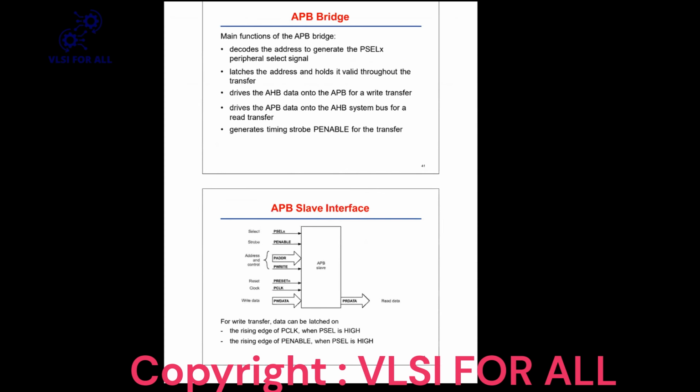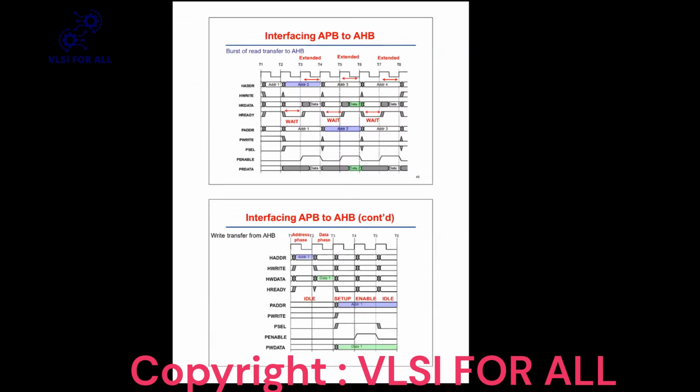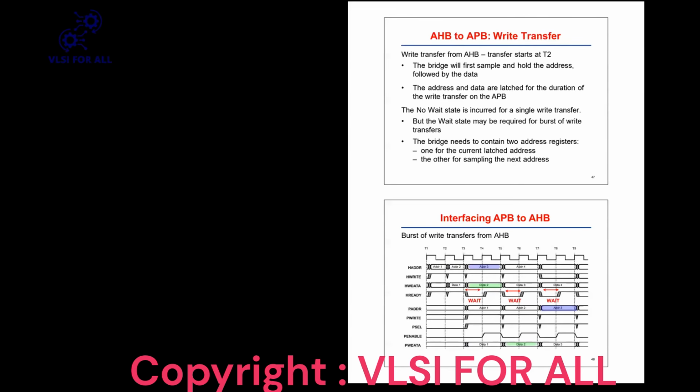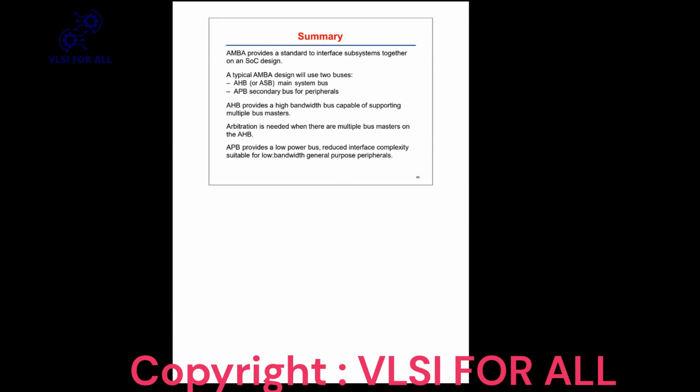Like I initially said, let's say we are using AHB for the processor, and one of the peripherals is a low-speed peripheral, so of course it will use APB. Let's say we have 5 clock cycles, so AHB will give 5 transactions in 5 clock cycles, although it requires one more, 6 clock cycles, due to the pipelining concept. But just assume that for 5 clock cycles it is giving 5 transactions, but APB requires 2 clock cycles to handle one transaction.